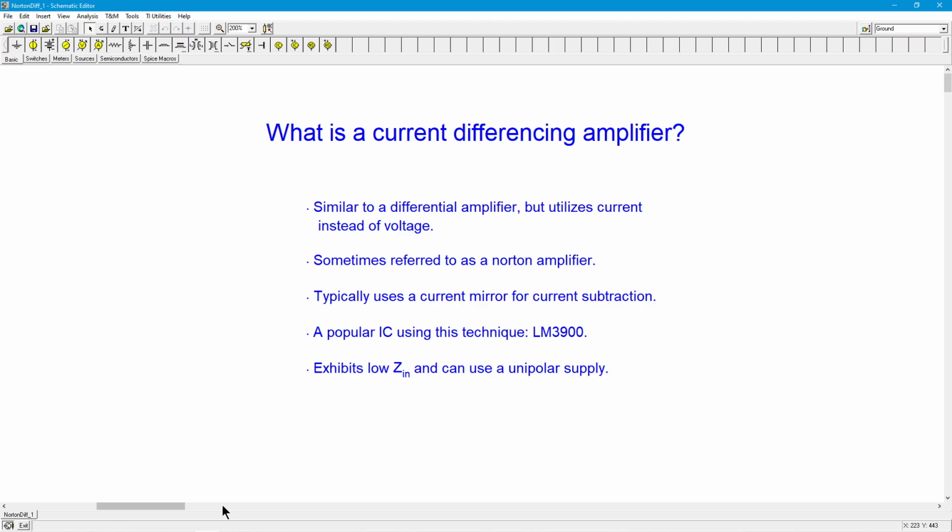It's kind of a unique little circuit in that it can run on a single polarity power supply. You're going to have to add some extra things to make a dual power supply, a normal op amp that we're used to. It has some kind of weird little quirks to it. They were very inexpensive and people liked them. But there are some quirks compared to your average amplifier, which would include the fact that the input impedance is not necessarily all that high. It depends on the design.